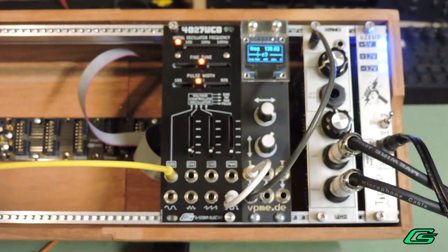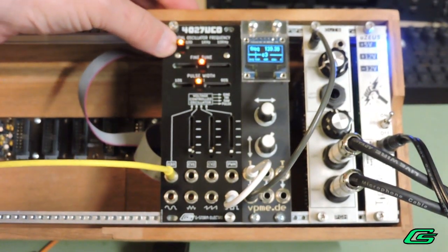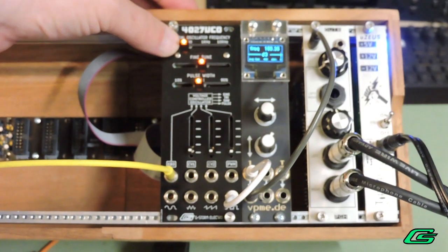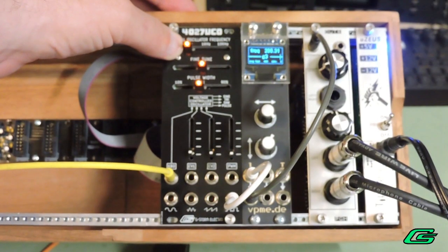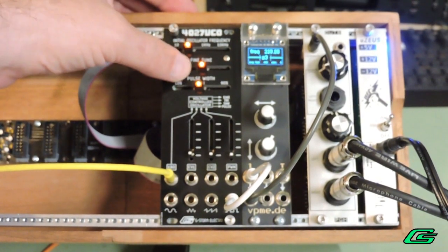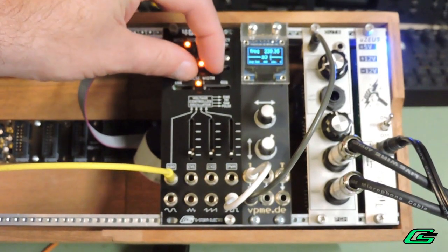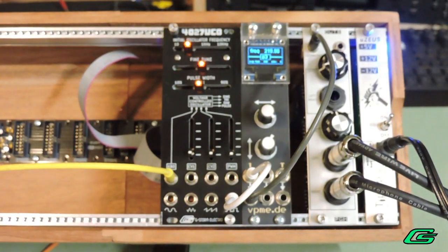Since my analog VCO has had a chance to warm up, I want to tune the oscillator, such that when I play an A on the keyboard, the oscillator pitch is also an A note. My oscilloscope has a tuning mode where it shows me the pitch the oscillator is putting out. I'll play the middle A key. I'll adjust the fine-tuning control for getting it even closer. Now when I play up and down the keyboard, the oscillator should be able to track each note.